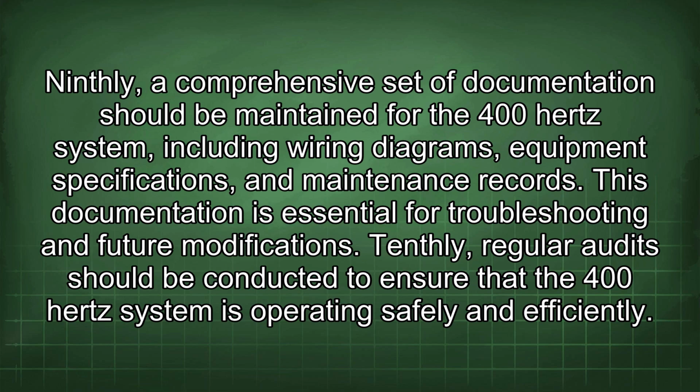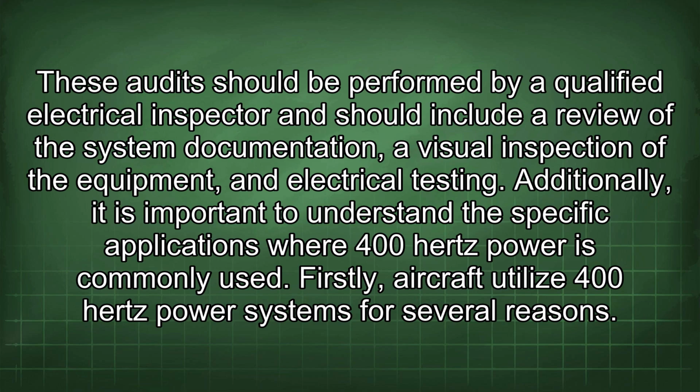Tenthly, regular audits should be conducted to ensure that the 400 Hz system is operating safely and efficiently. These audits should be performed by a qualified electrical inspector and should include a review of the system documentation, a visual inspection of the equipment, and electrical testing.